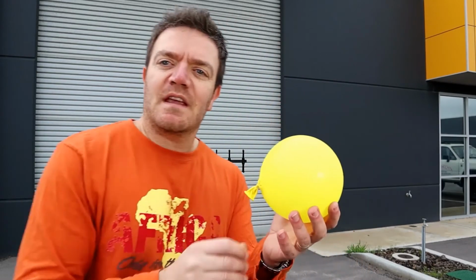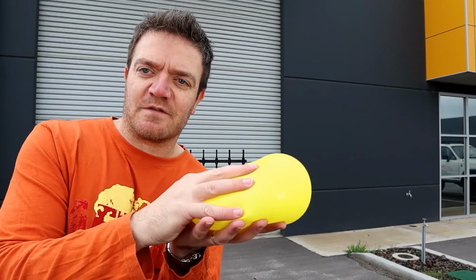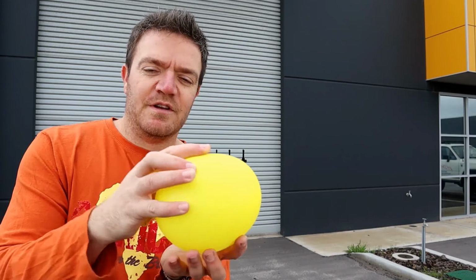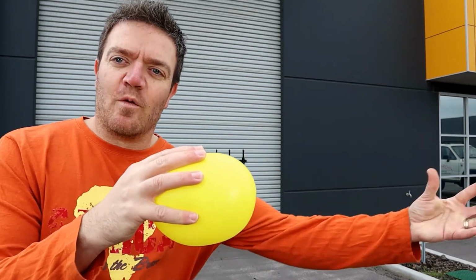What it does, again, it has antenna gain, quite a lot of antenna gain to the front. That's something you can manage. You can make it higher or lower, and there is obviously, as always, a design impact that gives you benefit or specific parameters that you can use. Coming back to my balloon, so 0 dBi, my isotropic source. What a directional antenna does, if I look at it from the back, I basically take away air from the back and I start to squash it through the front. So you get this effect that you take away from the back and you squash through the front. So forward gain is what's necessary.